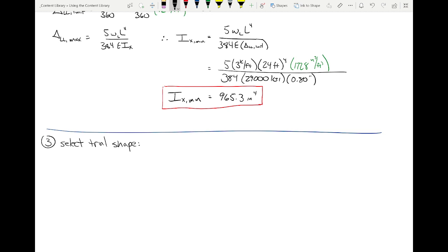Okay, so remind me, what was our LB again? 24 feet. And now what we need is an MU over CB. Why are we dividing out CB again? Does anybody remember why? The graph is built based off of a CB value of 1.